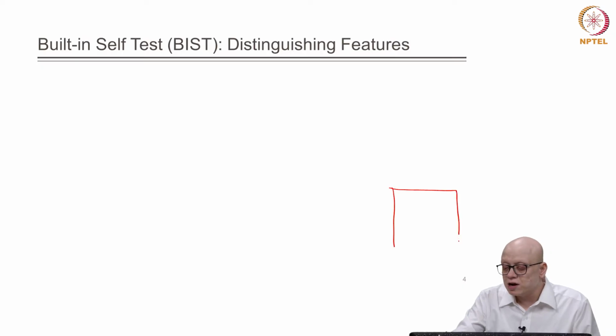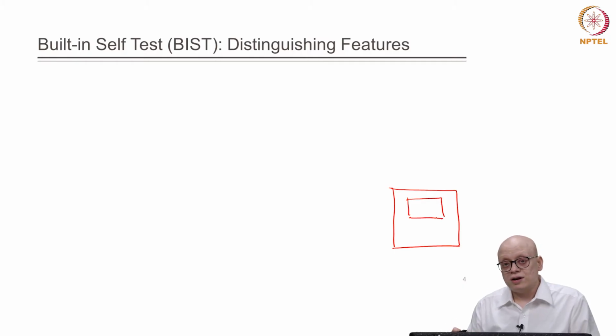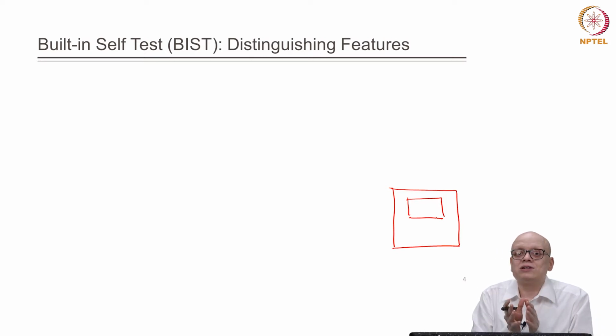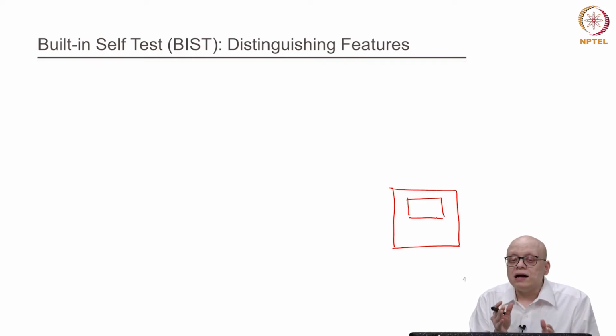Now, to have a BIST infrastructure within our design, it will require some cost in terms of hardware, meaning that it will occupy some area and so on, right. So, we want that the BIST infrastructure that we embed within our circuit is not taking a heavy cost in terms of area and in the infrastructure of the chip itself, right.